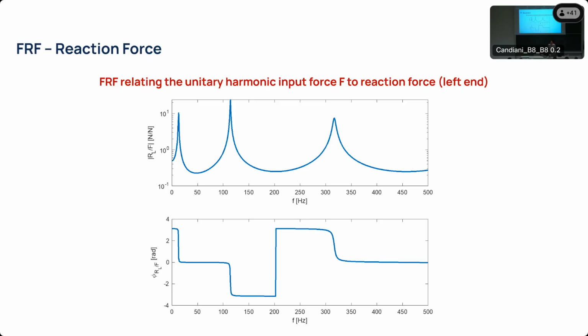Because if you remember, this is an amplitude phase diagram, so amplitude is always a positive value, and the eventual sign is carried by the phase. And why should we have a 180 degrees phase at zero frequency if we just give a positive force to our structure?